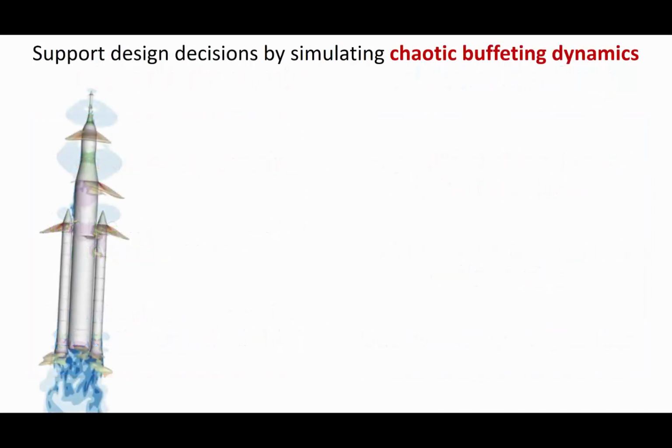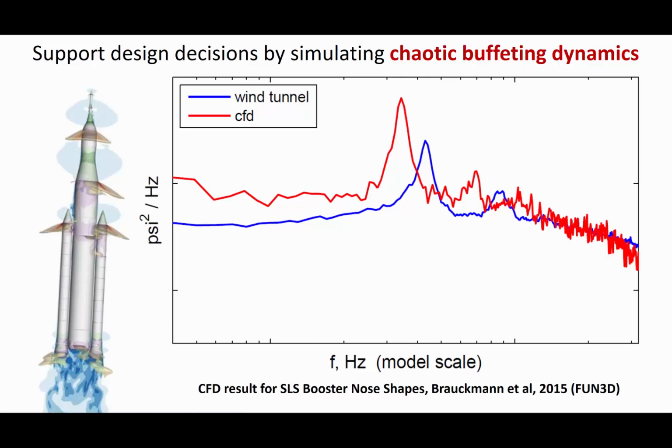And particularly, the type of simulations people are doing, for example, in buffeting, is already used in design decisions, for example, by NASA. So NASA is designing this space launch system, right? A lot of us know that. But a few of us know that it encounters buffeting problems, the same kind of buffeting problems airplanes are under. Because the connection hardware between the main part and the solid rocket boosters, there is a shockwave sitting here, and there is also vortex shedding over the attachment hardware.